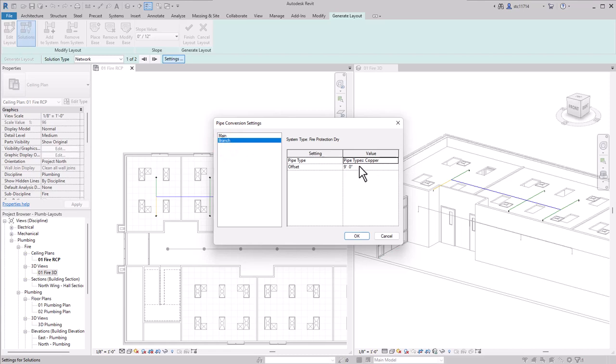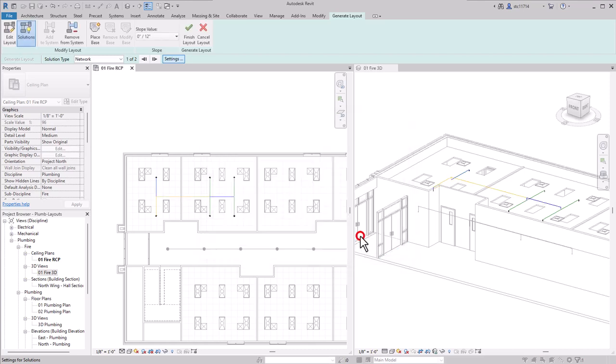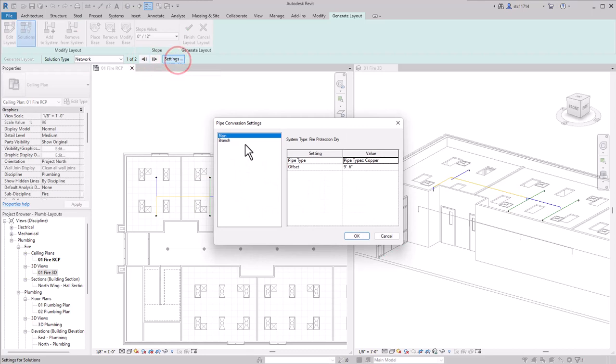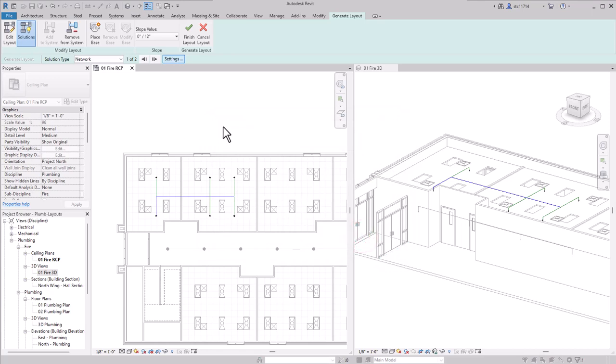Now in the book's exercise, they're going to have you start with a 9 foot for these branches. That is going to cause a lot of problems. We only have 2 possible solutions, and there's a lot of problems with both of them. And the book is just going to have you go back into settings and make sure you set that branch to 9 foot 6 as well. Now it should work a lot more smoothly.